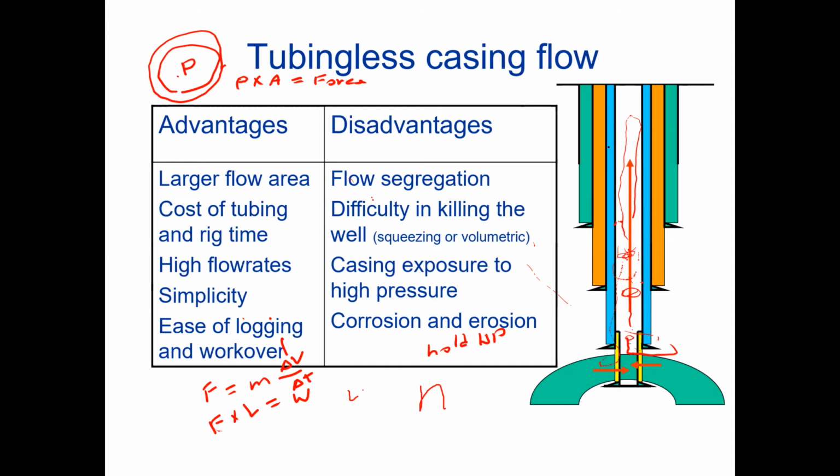That is, you inject some mud and wait for the mud to settle down and then remove the pressure, and then inject more mud and reduce pressure, inject more mud, and gradually fill up the well, the conduit.